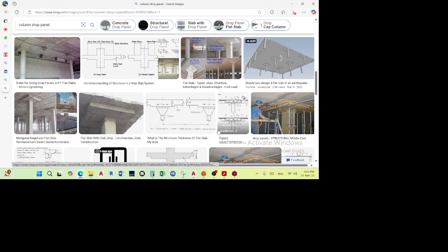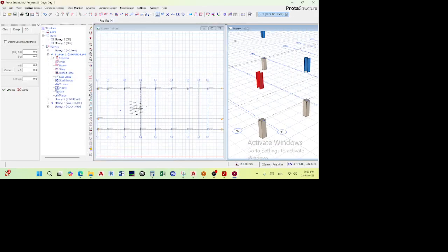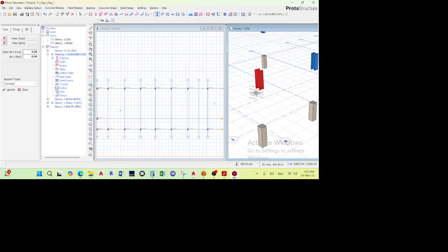But then, okay, so too much. So let me go to where here we are trying to reduce, right? We are trying to reduce from the wall plate to the ground, and we've estimated that it's about 3,800. Yeah. So here on delta z, it's going down. So I'll add a negative, and I'll say 3,800, right? And then I'll update it. Let's see what happens.